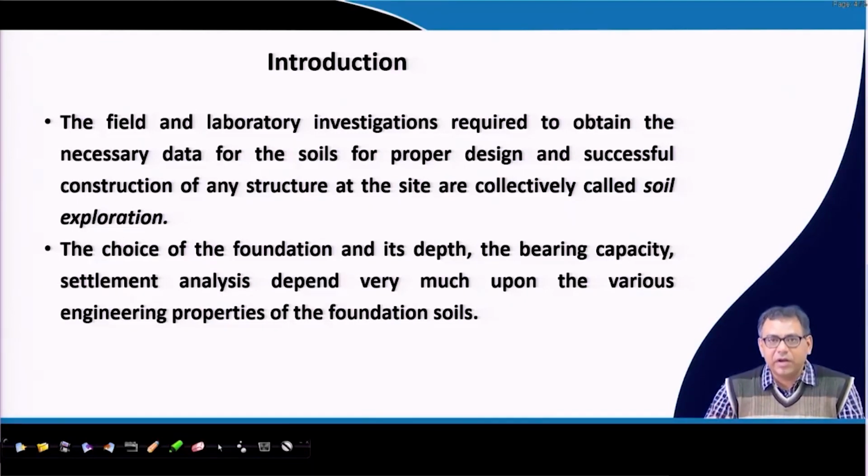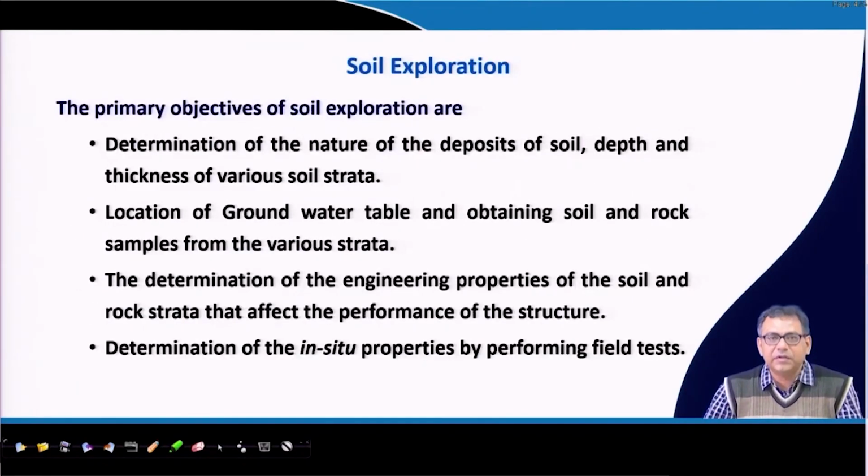That is why soil exploration is very important, and the objective of soil exploration is to determine the nature of deposits of soil, depth and thickness of various layers, then location of groundwater table, which is also very important, then obtaining rock or soil samples from the site.